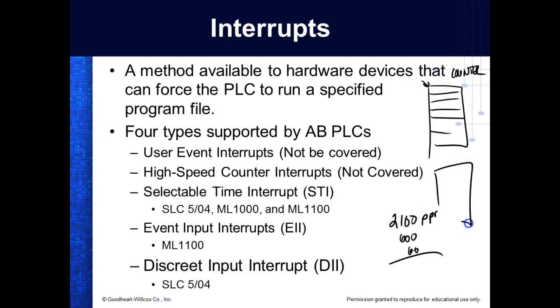Later I have another counter, and we insert another subroutine that handles that counter. Now the problem is that each one of these instructions takes time to execute. What was happening is we would put these software counters on an encoder, and it would lose counts because it could not keep up with the count.